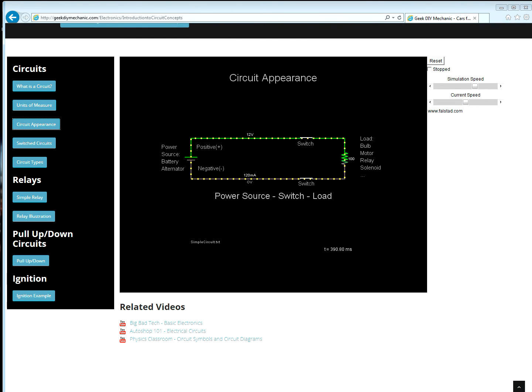That's considered the load in the circuit. Notice that all the voltage was used up by the load by looking after the load and noticing 0 volts. So 12 volts are here, travels along, the load consumes it all, and 0 volts are going back to the battery. All the voltage is used up.